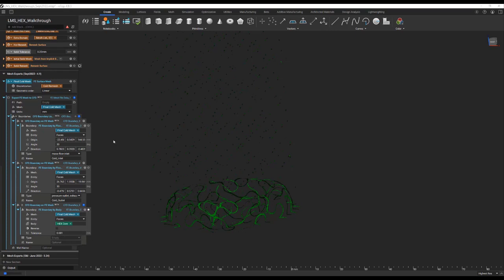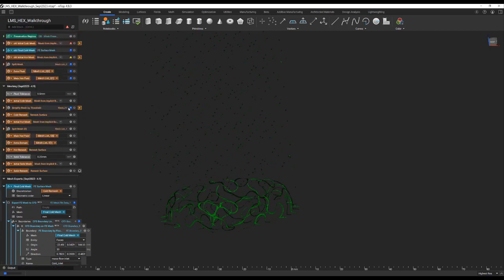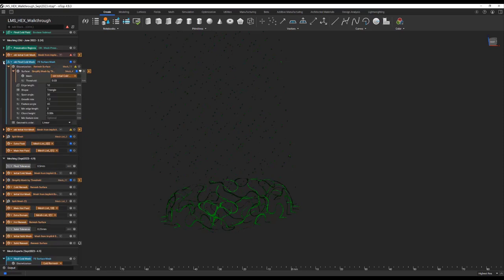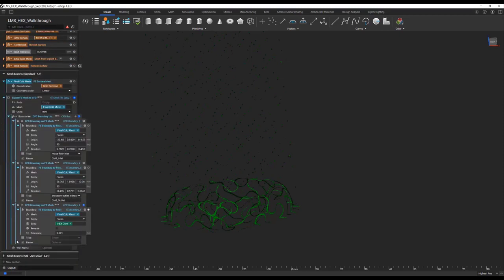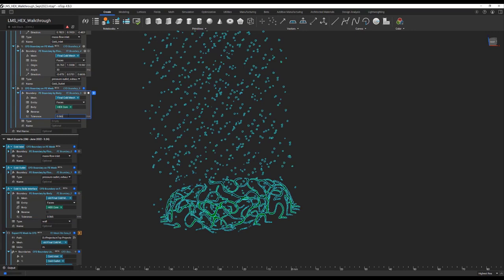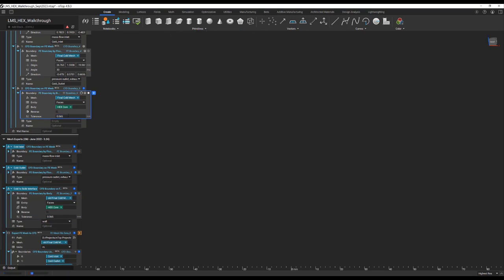So sometimes it's going to be a little bit of a guess and check, but because we did this previously on this example, if we scroll down, we can see, okay, we used 0.065, so I'll copy that, put that value into here, and we should see that we've captured more of the elements that we want to transfer heat across from.